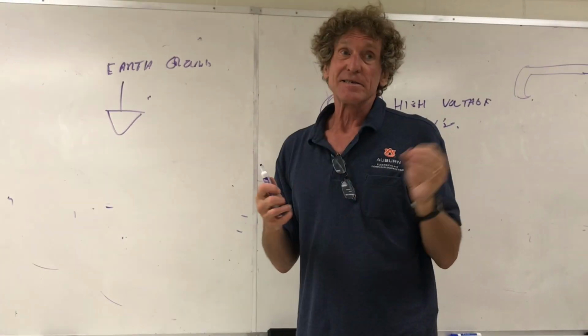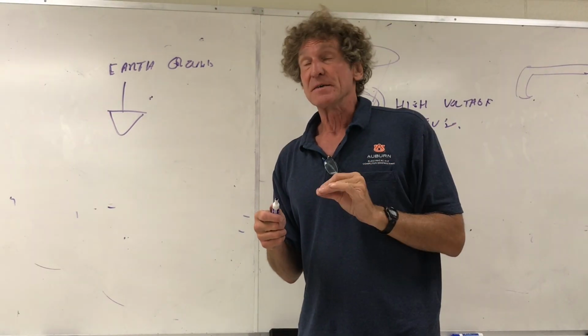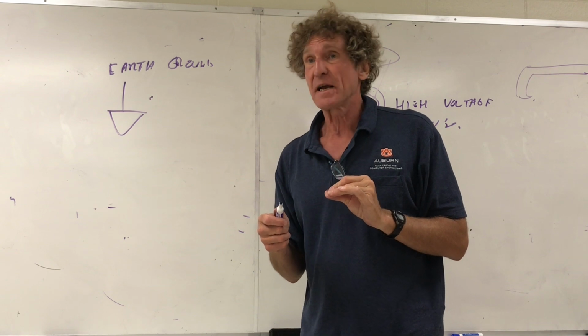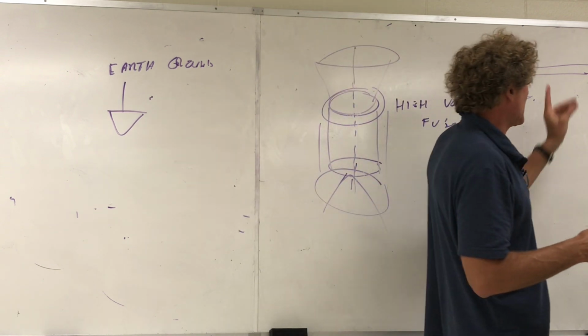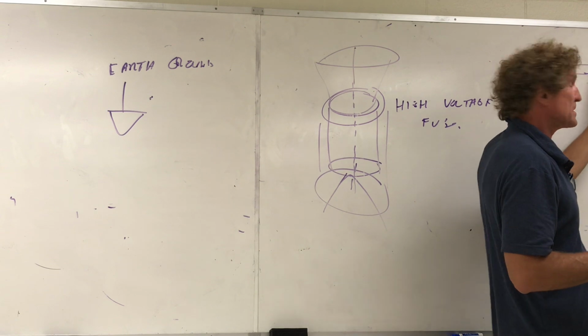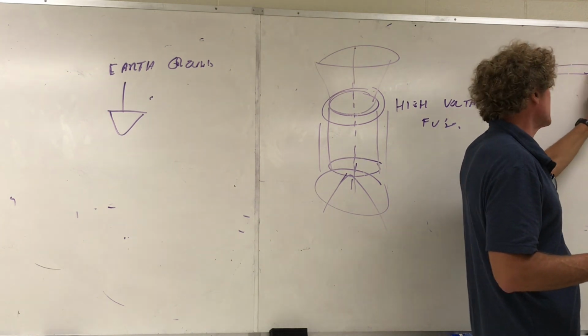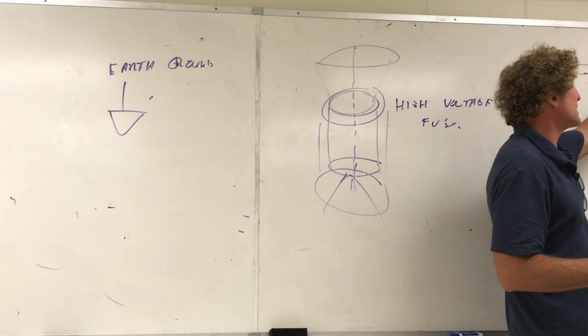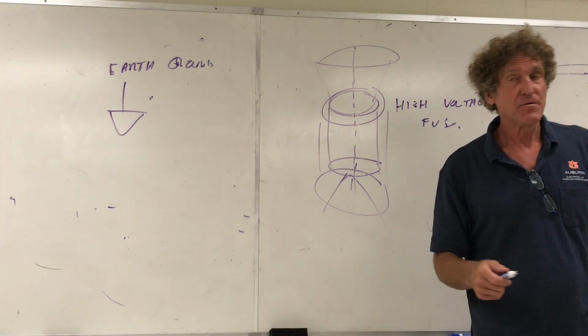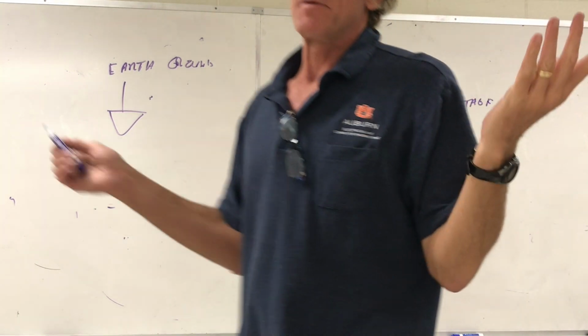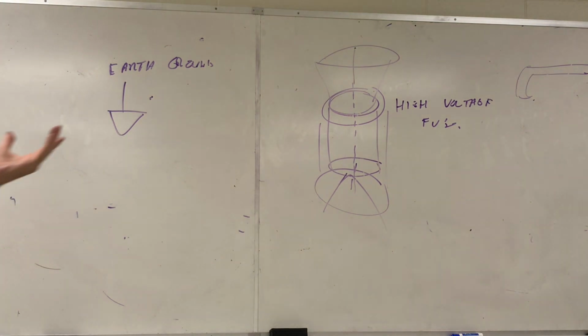So the earth ground is critical for something like this, because frankly, if worst case scenario, you ever get a live arc and it goes over this 10,000 volts, and it goes over this and over the water resistor. If you're not in the earth ground, God knows what may happen. You can start fires, who knows what.